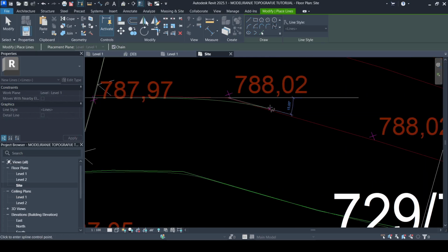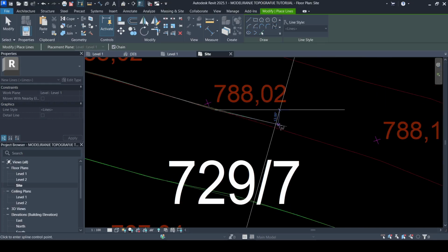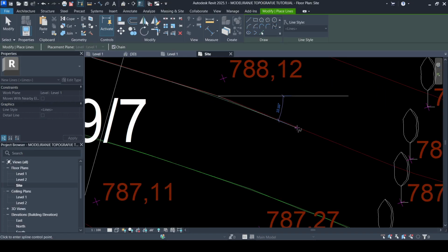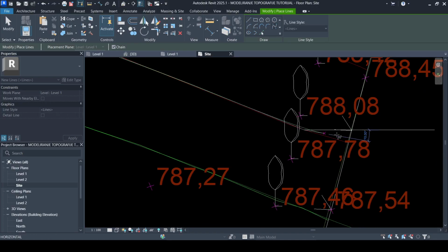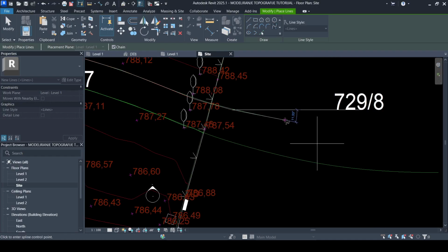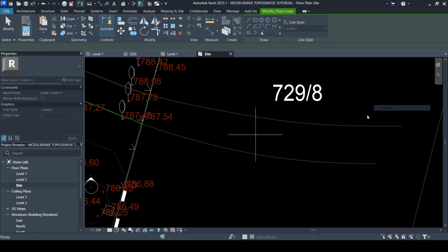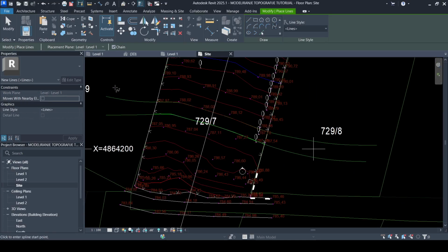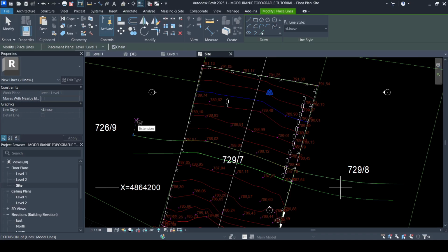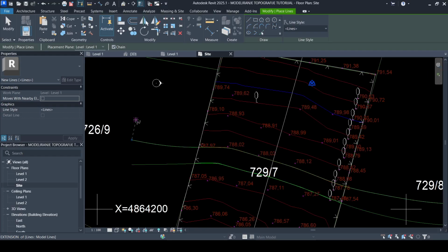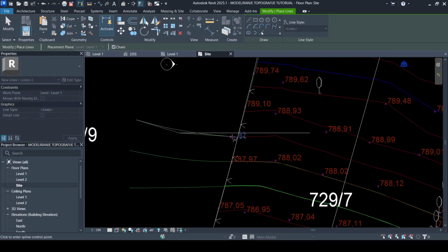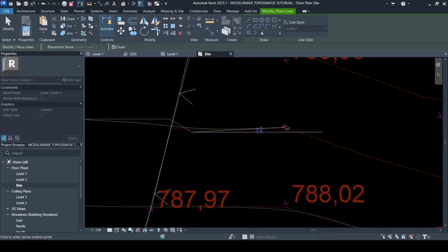As I said, we must follow these lines here. The most important thing is here. Even if you have the topography lines out of our property line here, when you create directly from the CAD file, often an incorrect toposolid surface appears. It isn't a smooth surface. So if you want to create a smooth surface without incorrections, you can use this method. Okay.